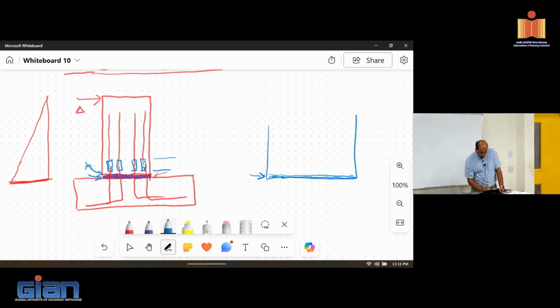In this part, your moment is still the same, but you have a lot more steel in there, so the bars are not going to experience the same amount of tensile strain. Typically, whatever you put is a passive reinforcement, so the crack just opens up before the reinforcement kicks in. The cracking will happen, but because you have plenty of steel, the crack cannot grow again. You mean in this region?